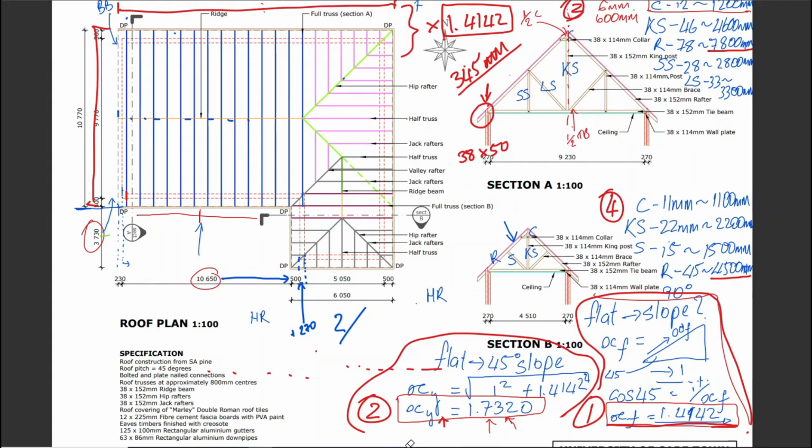So that is what I did. I scaled it, and then I applied these factors, and then you get, I don't recall the actual value, but then you apply these values here, and what is quite important to make sure you don't get caught out by, those ends are longer, because they're actually going to use this factor. So you need to recognize, because it is part of this hip rafter that used factor Y, it also means its ends need to apply the Y factor as well. You can't apply the X factor to the corners because they're traveling on a 45-degree angle, and it's slightly longer.